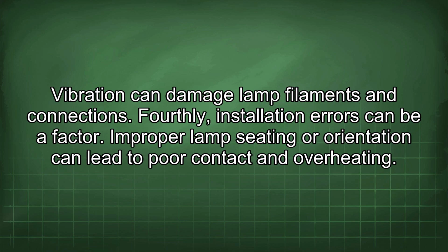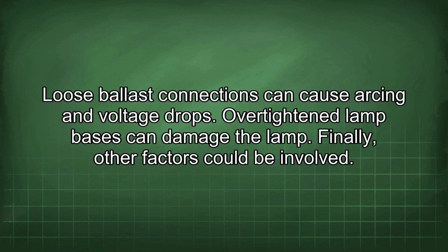Improper lamp seating or orientation can lead to poor contact and overheating. Loose ballast connections can cause arcing and voltage drops. Over-tightened lamp bases can damage the lamp. Finally, other factors could be involved.